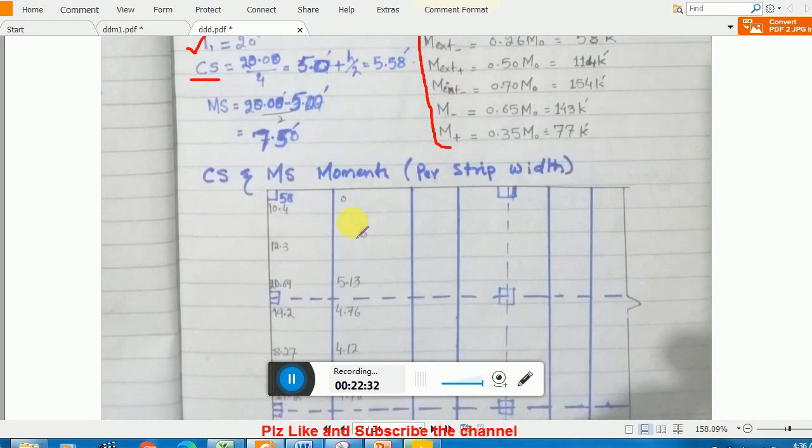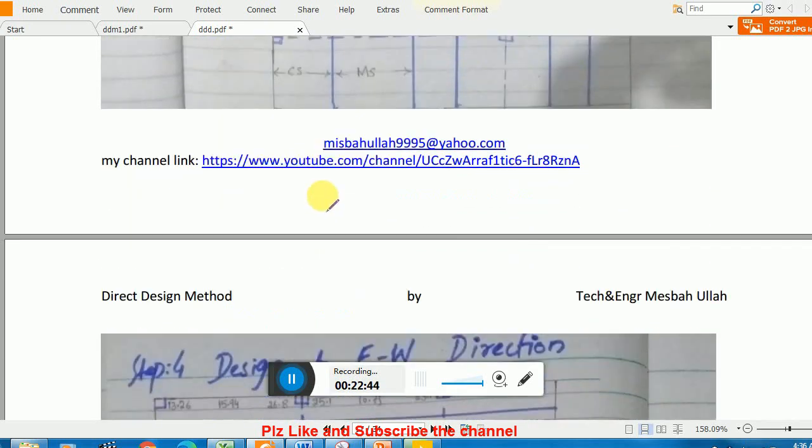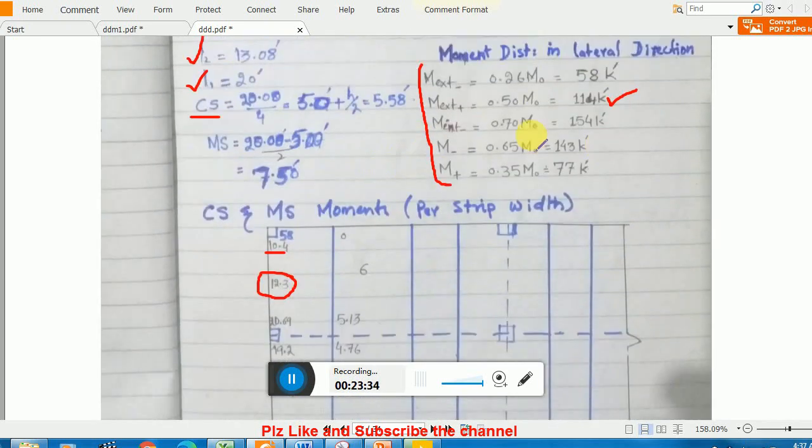I again shrink the things. You see, this is 58, the actual value is 58. Now divide this by the column strip width, that is 5.58, you got 10.4. The same way, this is M exterior positive, remember M exterior positive.